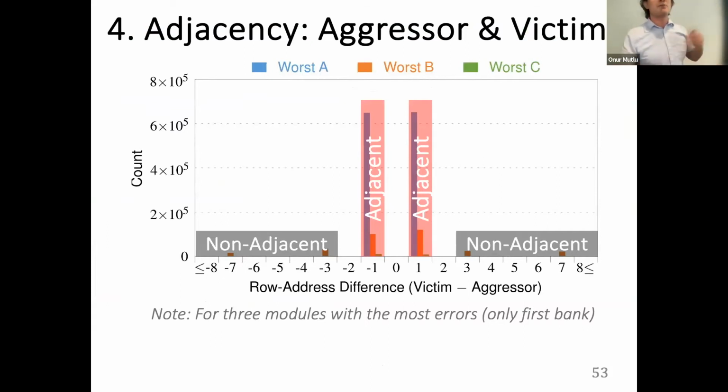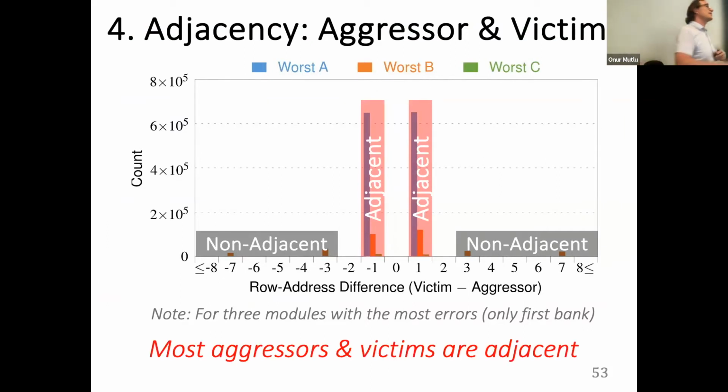This means we hypothesize that there's some internal remapping of row addresses going on in DRAM for fault tolerance reasons, for other reasons, etc. That logically you're not adjacent. Now, what's the significance of this? The significance is that if you want to implement a defense in the memory controller, you don't know where the rows are. You need to figure this out first. So you need to reverse engineer, or you need to come up with an interface where the memory exposes the adjacency of the rows, which DRAM manufacturers are, in general, very against doing, let's say. And we can talk about that also.